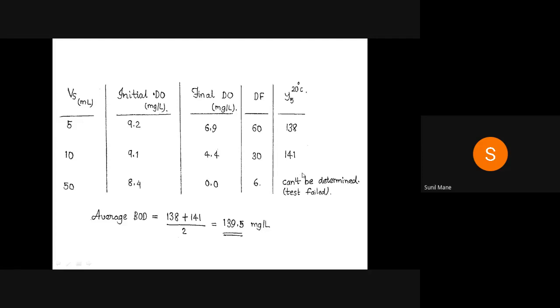Now, practically, instead of 22 days, we have taken 5 days results, that is 60 to 70% results. Even after getting those 5 days results, practically, if the wastewater is available on day one, we have to take action or carry out some kind of treatment, but we will come to know the wastewater strength only about the fifth or sixth day. So practically it would be very difficult for us to take action so that the treatment of the wastewater is carried out.